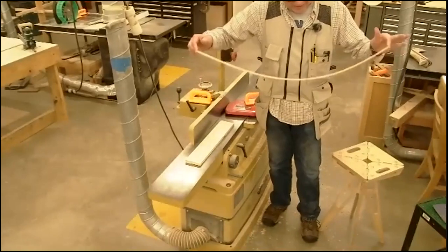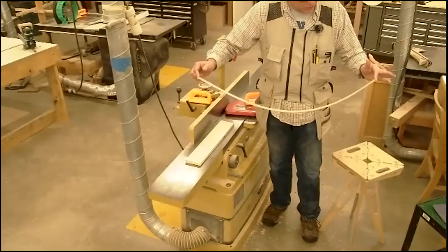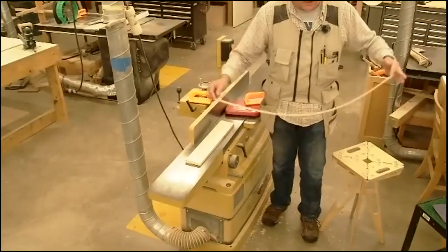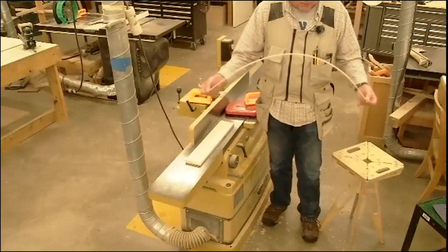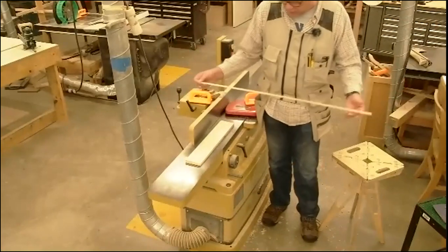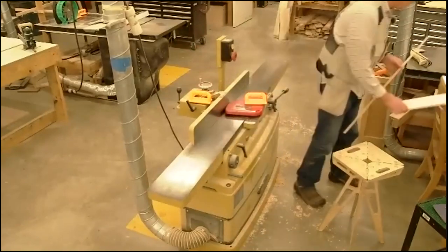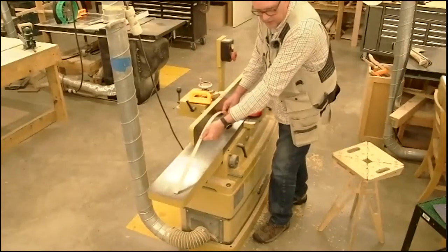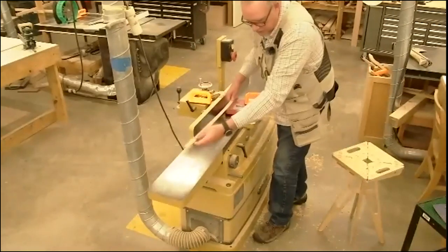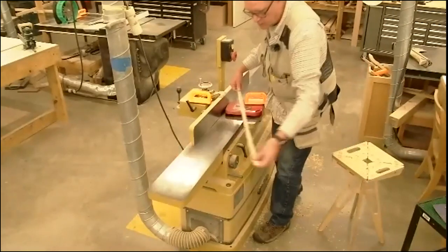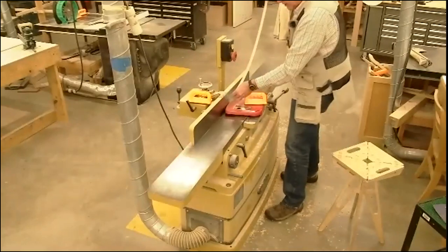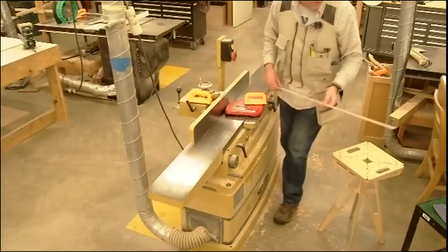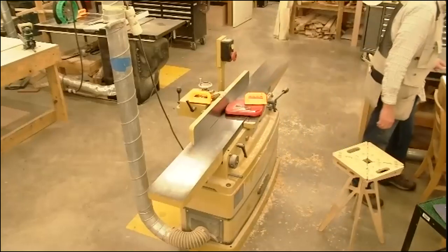You would never put this surface down on the joiner. If you do, you've taken a chance of that board rocking as you're going through, and you're not going to correct the bow. What you want is like this. In other words, the board should touch at the front and the back. It shouldn't touch in the center. If you do it like this, you're taking a chance on it just rocking as you go through. Like I said, it's not going to fix it. So what we've got is a couple boards here.